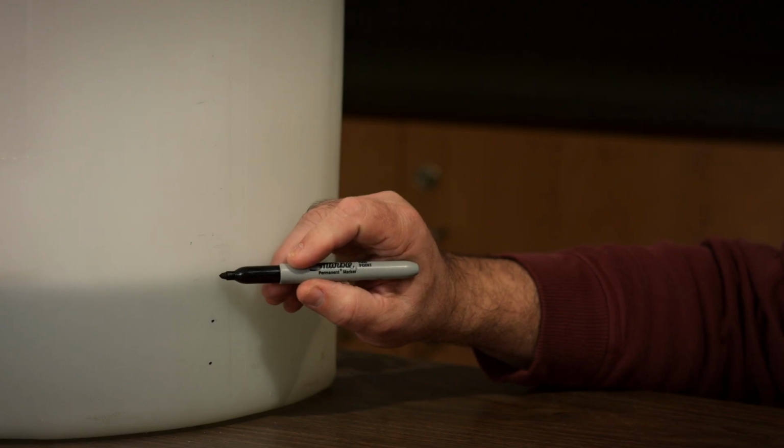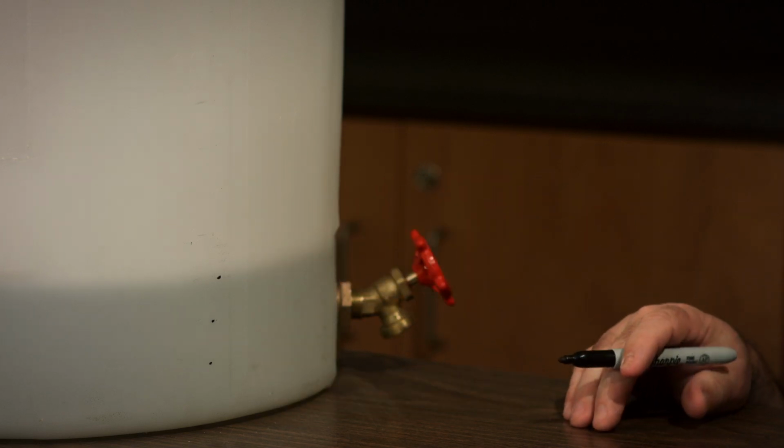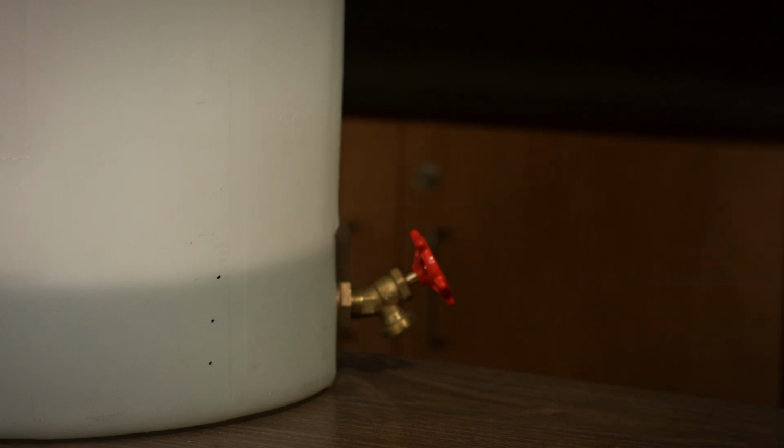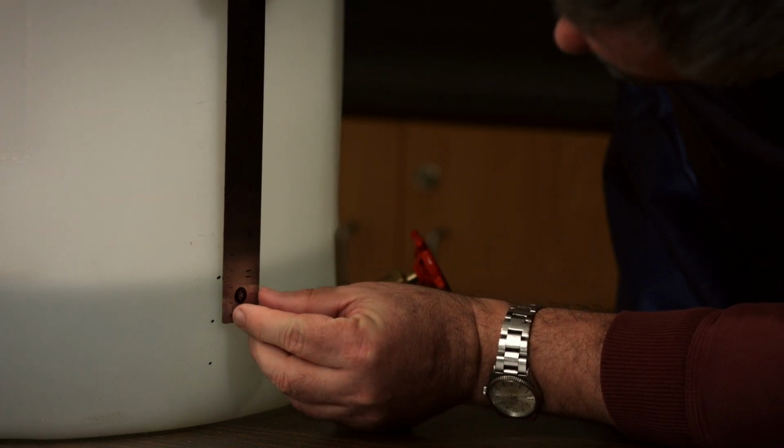For a uniform cylindrical tank, simply use a tape measure to graduate the tank into equal volumetric segments, that is 5, 10, or 20 liter segments. To do this, we need to add a known volume of solution to the tank. We can then measure the rise of the liquid in the tank. For this demonstration, based on our tank size, we are using 5 liter increments, which result in a 26 millimeter rise in our tank level.